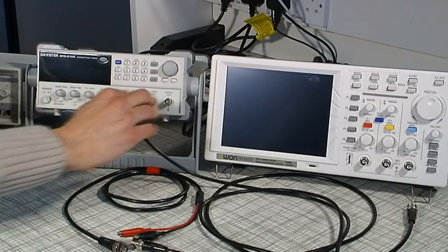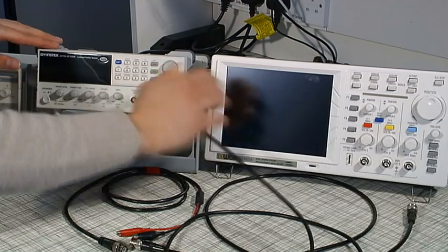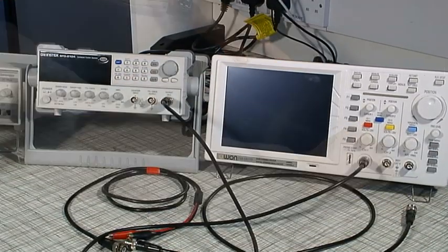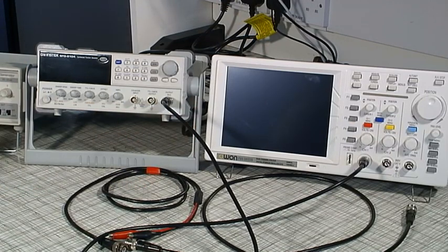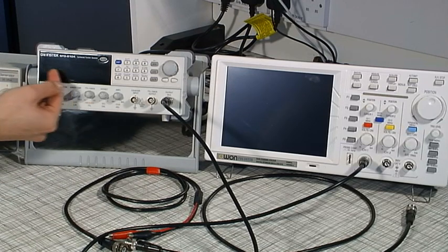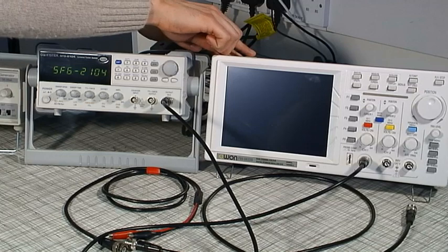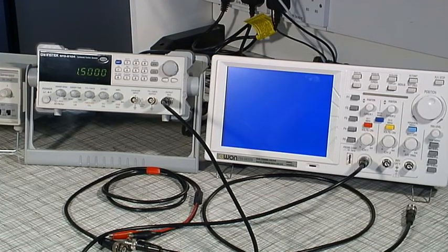Here, the function generator is connected directly to an oscilloscope. If you want to know more about the oscilloscope, please visit the relevant section of the video. Make sure the tilt stands are set up comfortably so the controls are easy to access and that the display is clearly visible. Switch on the function generator and the oscilloscope. The function generator starts up in the last state which it was used.